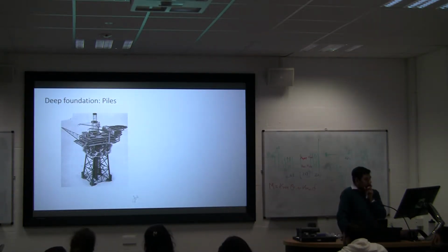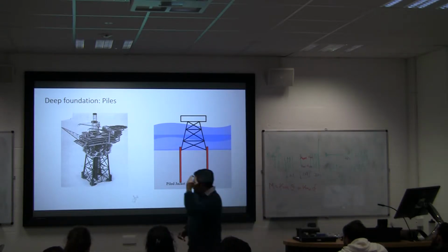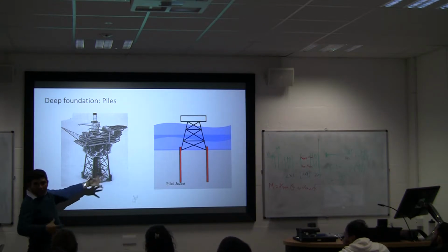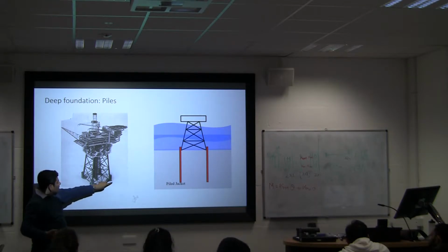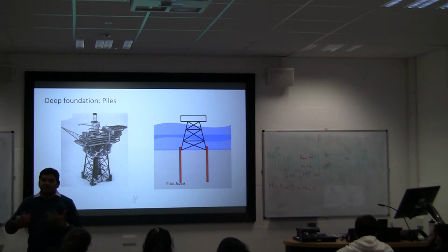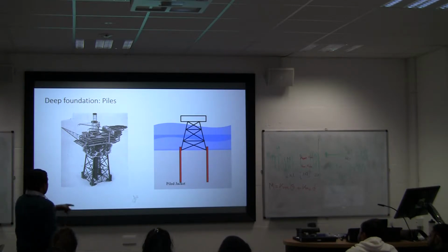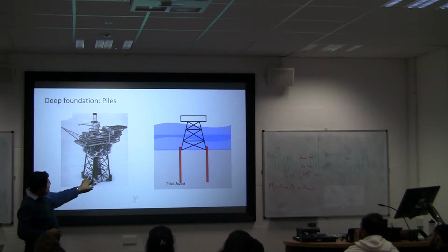So here's one application, our foundation. How does it work? You see here, effectively, you have this jacket, what I showed you before, this big structure. It rests on the seabed. They're typically 4 legs. Each leg will have 3, 4, 5, 6 piles, depending on the location, right? So effectively, in a simplified way, this is the whole thing.